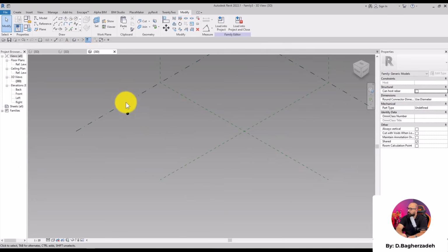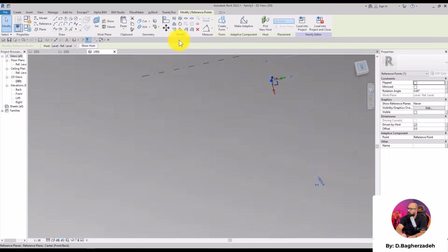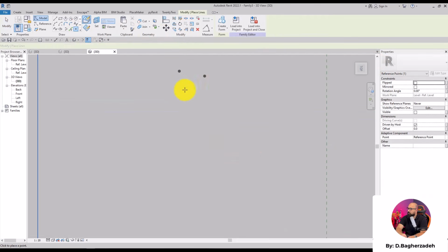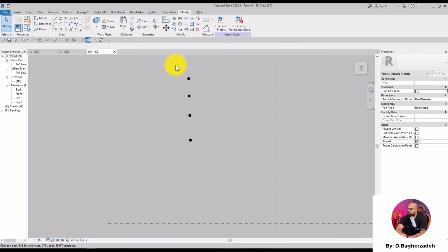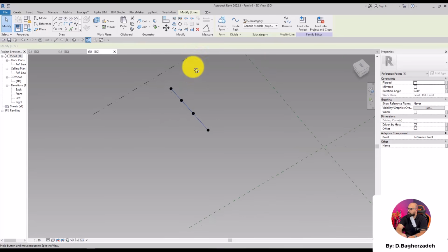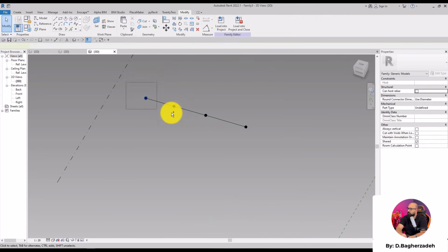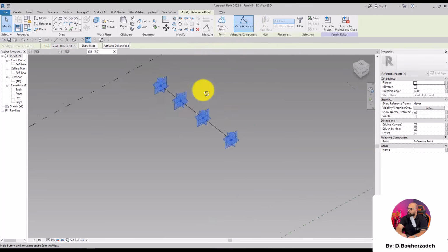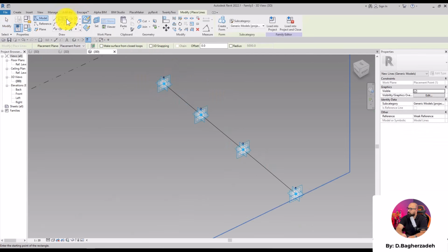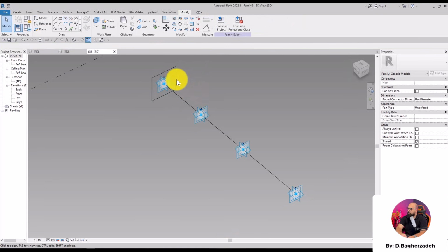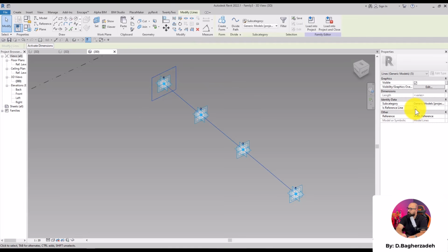Okay. So back to the adaptive template. I'm going to go ahead and set 4 points here. Now set the connecting line, then select the points and click on make adaptive. Okay, now I'm going to start creating my profile here. However, I'm not going to spend any time working on its parameters because, well, up to this point we have talked about it plenty and I'm sure you already know how to do that.